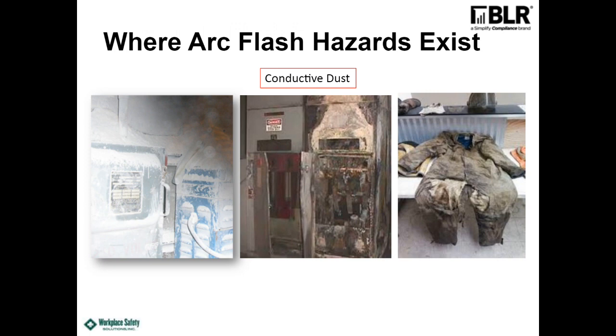Okay, this is dust levels, conductive dust. That's also an issue. So it's something to think about. If you have combustible dust or dust issues in the plants you're working with, you want to make sure that you mitigate those issues as much as you possibly can to prevent these things from happening. And usually there's a high level of maintenance, and you also have to go with class 2 hazardous equipment, class 2, class 3.